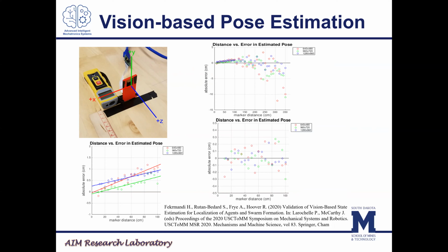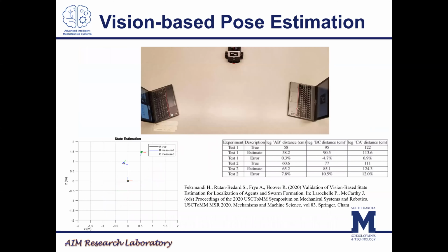But if we just look in the 0 to 1 meter range for distance, then we can see that there's some linear offset for each one of these. Now that just might be slight calibration inconsistencies or imperfect tag size. Either way, we can turn a 1.5 centimeter error, after we linearize it out, into a plus or minus 0.5 centimeter error on just distance, which is incredible.